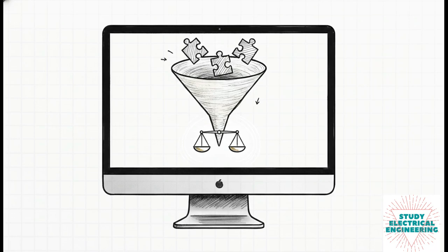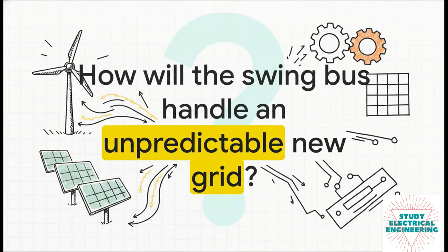Starting with those flat start estimates, engineers run loops using methods like Gauss-Seidel or the superfast Newton-Raphson method. They just keep updating the values over and over until the power mismatches shrink basically to zero, and the whole grid converges into this perfectly stable, beautiful picture. It really is an elegant mathematical dance, and it's successfully kept our lights on for decades.